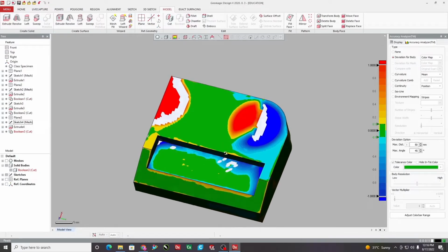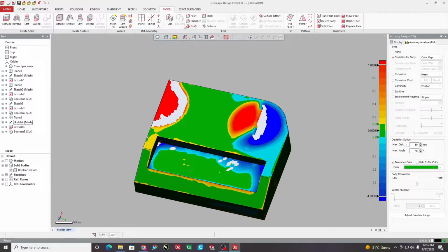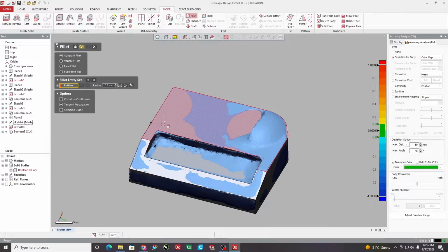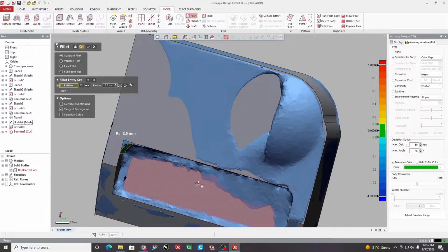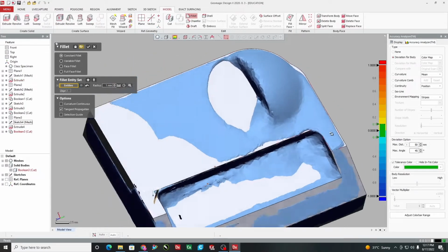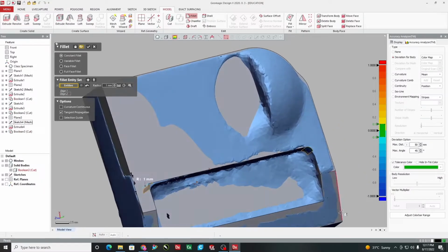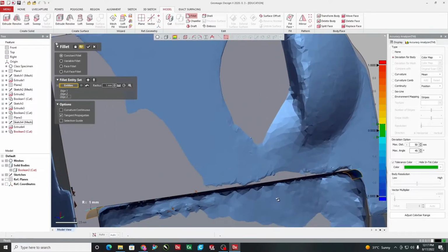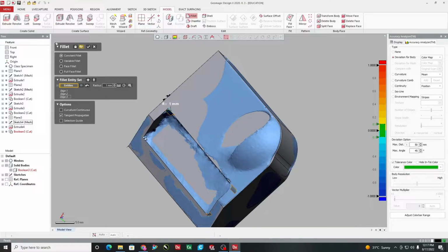So now again this green zone is showing the captured data using the scanner and the data that is required, how it is showing closer to it. This only gave us the dimension that the depth is 3 mm while putting the virtual plane there. Now we can put the fillets here. The fillets are also calculated from the captured data. So we will put a 1 mm fillet here. Each fillet is 1 mm. It is seen while putting the dots here in the original captured data. So those fillets are put in all 4 corners here, all 4 edges.